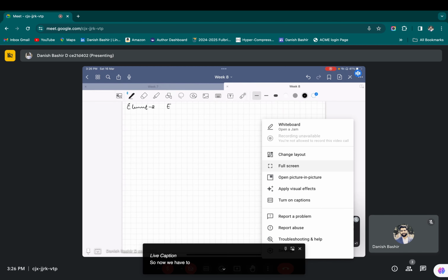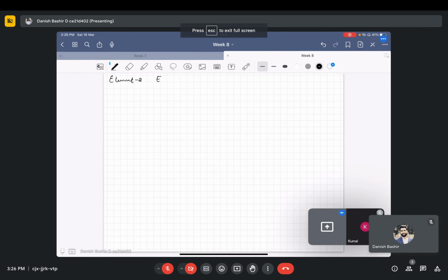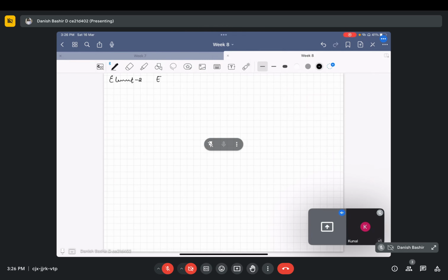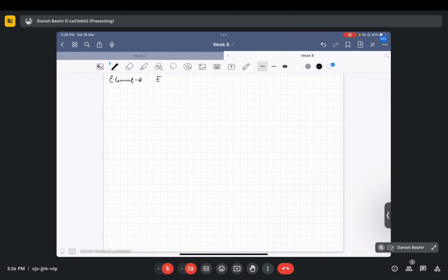So now we have to see the same equations for element two. We have to write them for element two. Let me do that. For element two it is again the same. E is equal to 200 kilonewton per mm square, but here the length is changed. L is 200 mm and I is equal to 10 to the power 5 mm to the power 4.